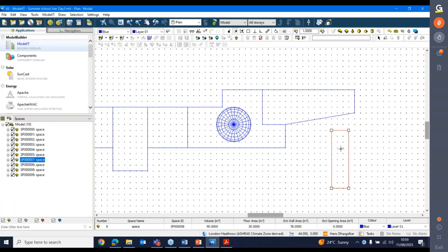Okay, so also, if you want to move or copy a shape or a series of rooms by a fixed distance, you can drag them by using the copy button with your mouse, but if you don't want to use your mouse, you can click on the copy or move button and then type in your dx command.